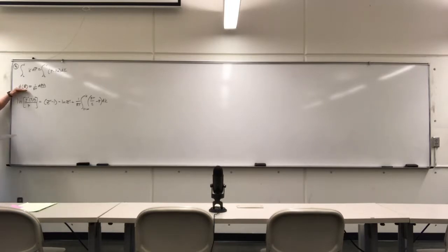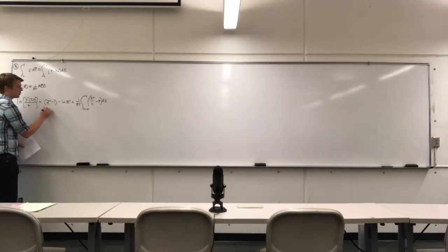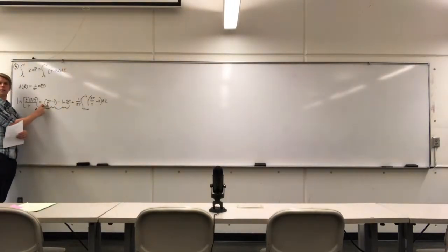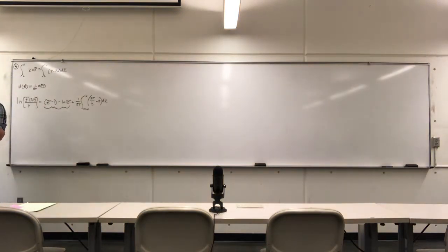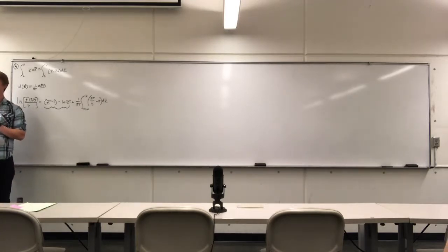So the compressibility factor is useful for a lot of the thermodynamic relationships that we'll be using, because oftentimes we'll see things that look like this here, where we'll have the compressibility factor of the vapor minus 1 minus the compressibility factor. The reasoning behind this is that most all of the relationships that we're going to be developing, we're going to go through an ideal gas state.